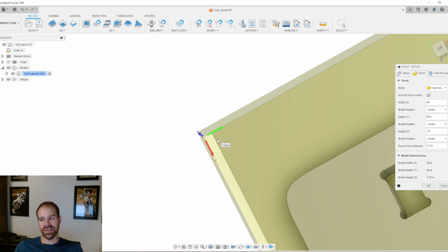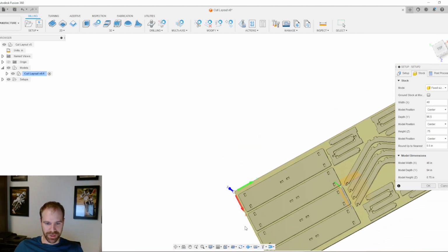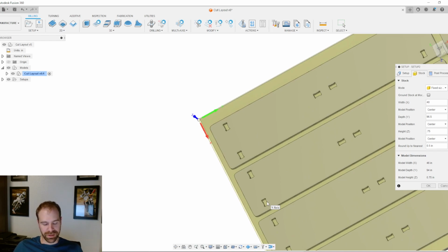the stock is off. So what this means is that when we go to set up our machine, if we actually put 0 for cutting out the part on the edge of our plywood, then if we hit the home button, it won't drive into our stock. It'll drive into nothing. It'll just touch off the bottom of the machine. But then when we go to cut it, it's just going to shift everything just a 1/4 inch closer to the edge, right? A 1/4 inch closer to this edge. But we've already given ourselves a pretty good margin here, so a 1/4 inch closer to the edge is going to be fine, right? In theory, that's how this is going to work, in theory.